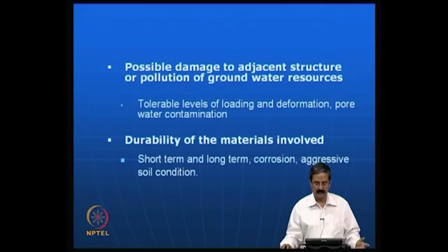So, if you just remove some amount of soil next to the ground, what happens? Actually, the apartment is standing because of the confinement effect. Now you removed some overburden of about 5 meters, then all the failure planes develop towards the excavation side, and the whole constructed building starts to tilt. That is a very dangerous situation.